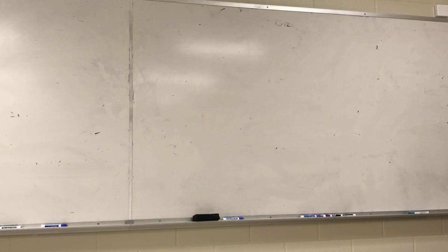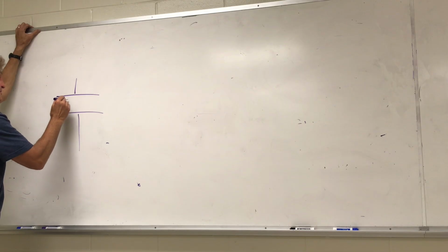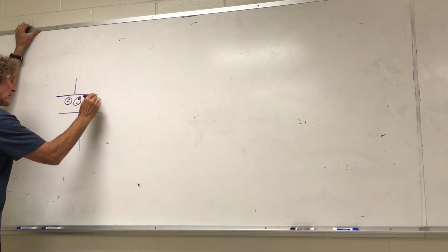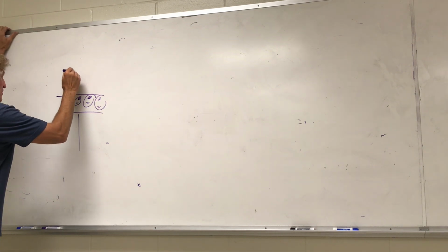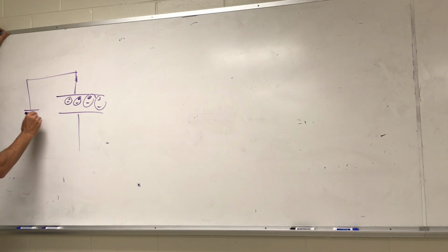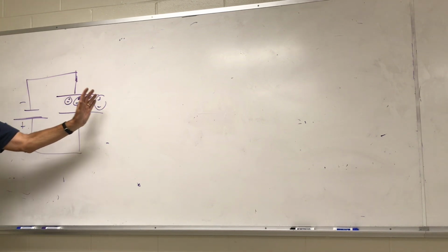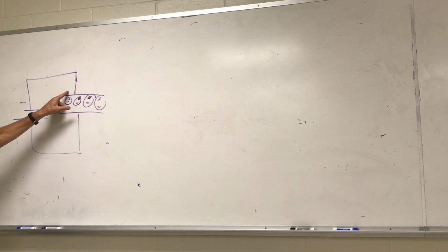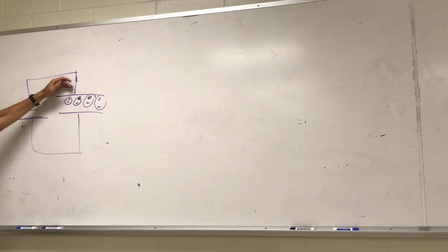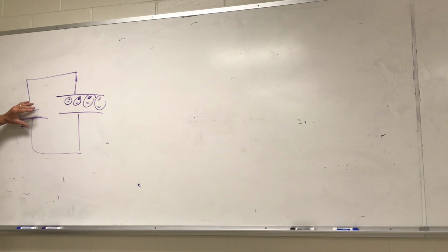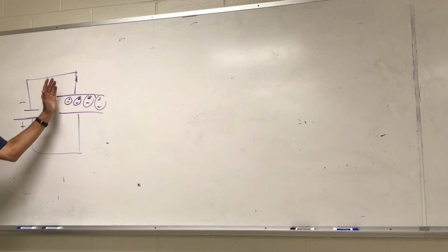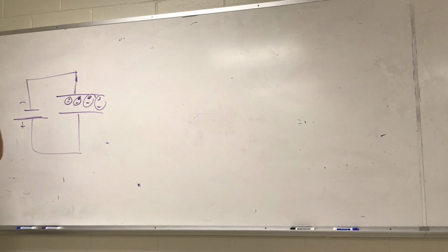So with an electrolytic capacitor, you're going to have dipoles in here, but they have plus to minus charge centers, and if I put a given voltage, I'm going to put the negative on top here. If I put negative, positive, they'll align themselves so the positive centers of these dipoles will be up this way and the negative will be down here. Now, if I changed the actual polarity, these things would flip, and they can flip. They can literally rotate. That rotation causes heat.